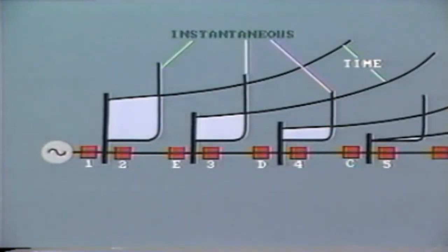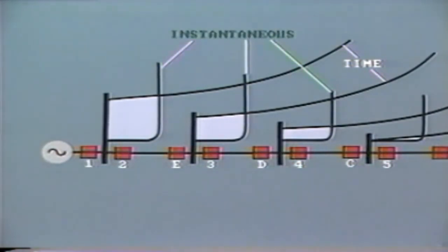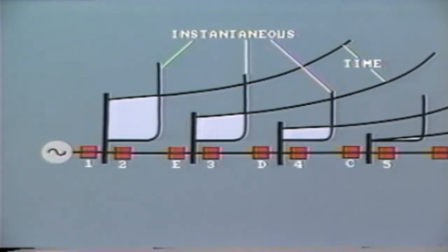The best method of resolving this problem is to install an instantaneous relay set to reach about 70% along its section of line. This means it will trip the breaker instantaneously for line faults which occur up to this point, but it will not operate for faults at the end of the line. We certainly do not want it to overreach and trip for faults in the next section of line. This would cause complete miscoordination.